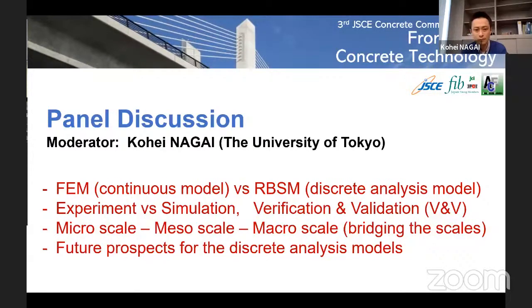The people that produce these slabs cut out 3-point bend tests, and depending on where the beam was cut from the slab, the properties were quite different. If you feed in the fiber positions, these discrete models do a good job. So a key point is knowing where the fibers are. If we know where the fibers are, the model can simulate.